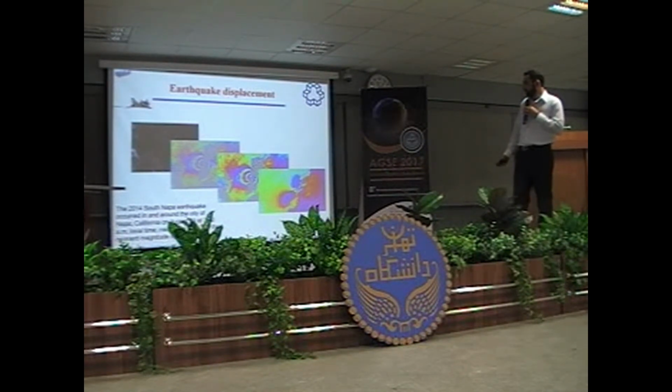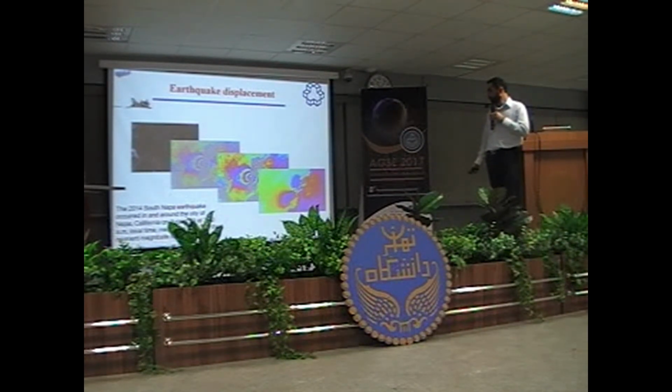Yeah, another example in South Napa, again an earthquake. You can generate the interferogram, you can unwrap it, and then calculate the amount of displacement.